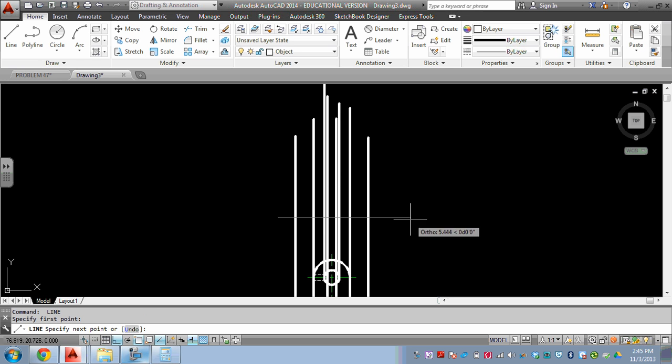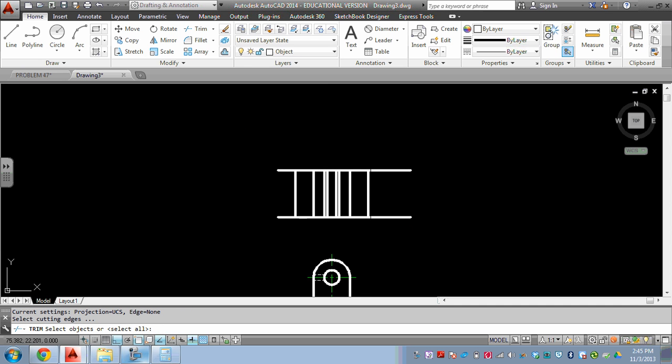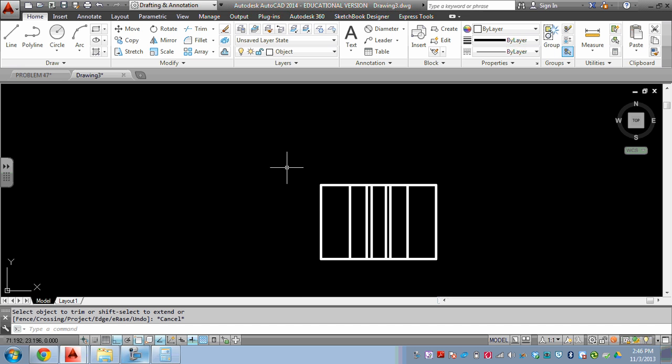So now the next thing I'm going to do is I'm going to say that's the front of our part. So that being our front of our part here, it says the part's too wide. So we'll go ahead and select the offset and do 2. Select this line and go up that way. I'm going to do a big old trim, TR. So I'm going to select that and trim all these features out. Repeat the command, trim. I'm going to trim these out. Okay, so now we have that.